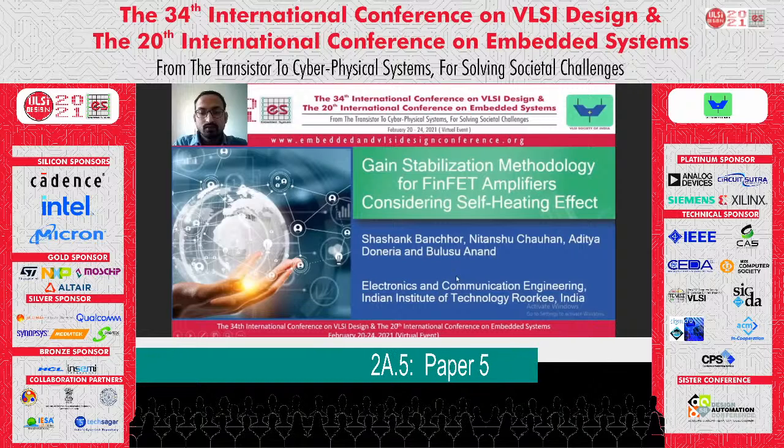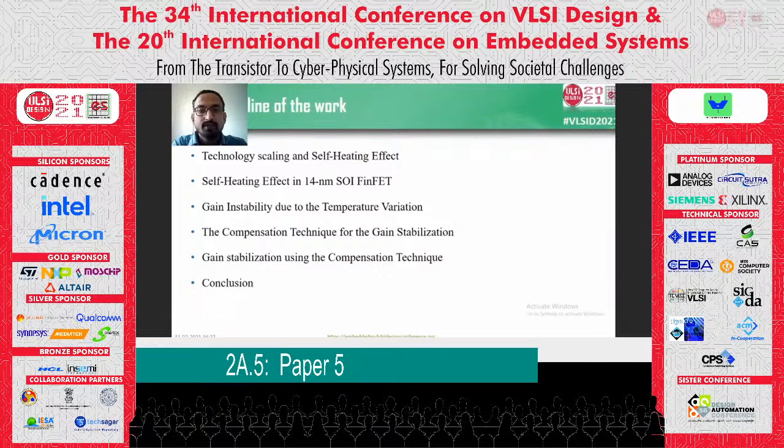We are working in the analysis of various physical phenomena in FinFET devices and their implications on analog circuits. FinFET is an industry adopted and very popular device due to its excellent performance in comparison to the planar MOSFET. However, due to the confined structure and box layer beneath the active region, self-heating effect appears as a critical and important concern in these devices.